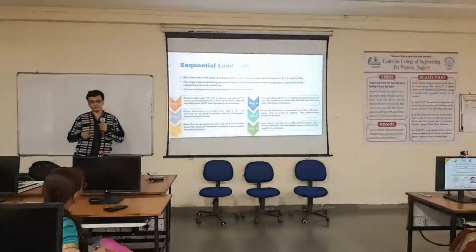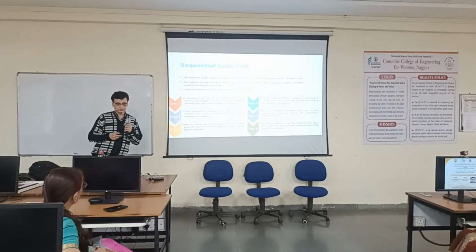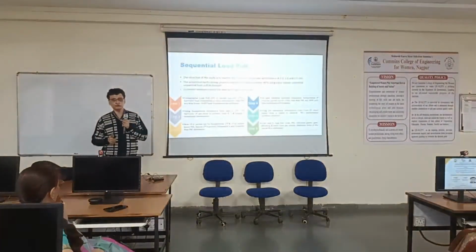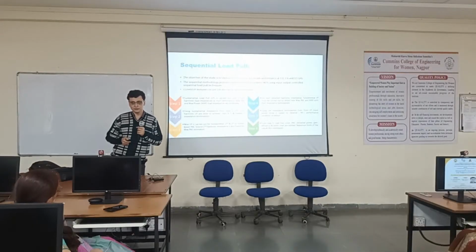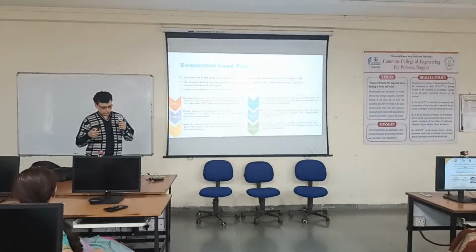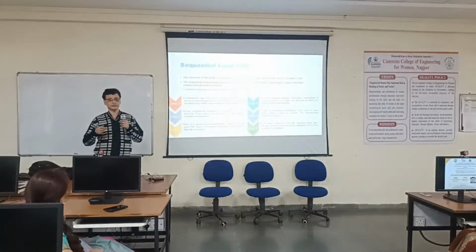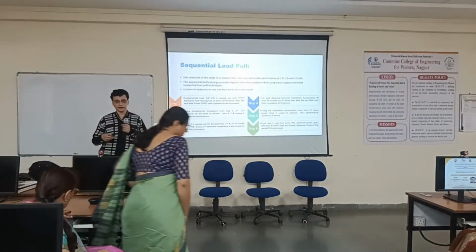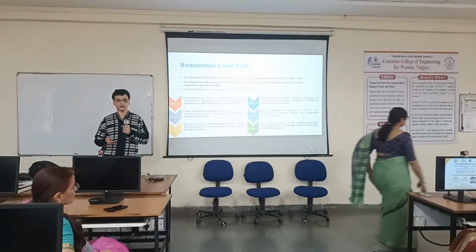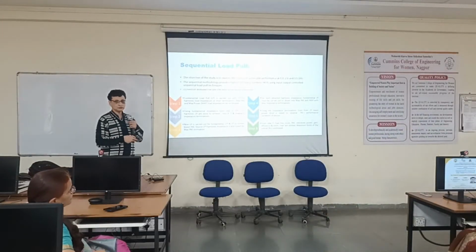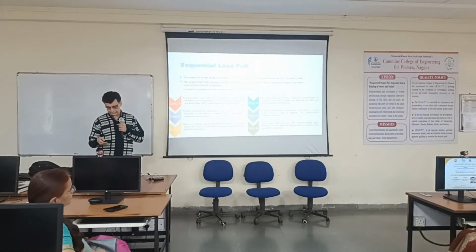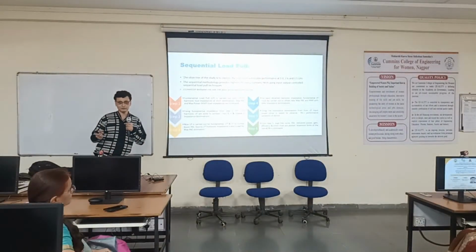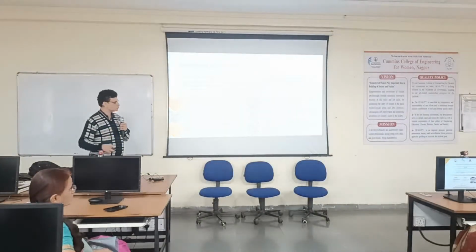When we try to fix a particular class of amplifier, how do we do that? There is a particular design tool known as load pull analysis. What we do in a load pull analysis is keep changing the load of the amplifier. We sweep the load over all possible values, and based on the one that suits our voltage and current waveform, we choose that. We adjust our bias voltages based on the load pull sweep that we do.